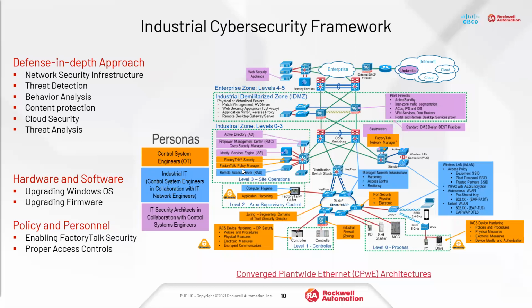If we're running Studio 5000 and you're still running on version 20, there's a version 20.05, which is currently the latest iteration that has all of the patches that we've done from a security, from a feature set point of view, without the need of having to change your control system at all. It's just an upgrade to the specific software package of Studio 5000 or RSLogix 5000.